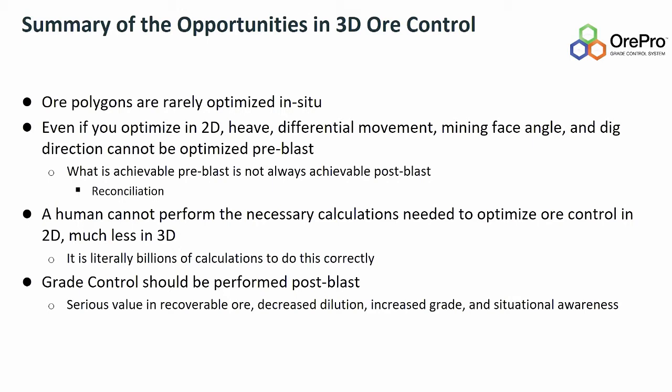I don't give you that per equipment because it really depends on your geology. From what I've measured, really short flitches, so I'm talking like 3 to 5 meters at most, you can sometimes get 90 degrees if you're using backhoes. But on big benches, it's a lot more. So 60 to 70 degrees is typical, but it really just depends on the geology. So you may even have in one pit 60 degrees in this area and 70 degrees over here. It's an input for you.